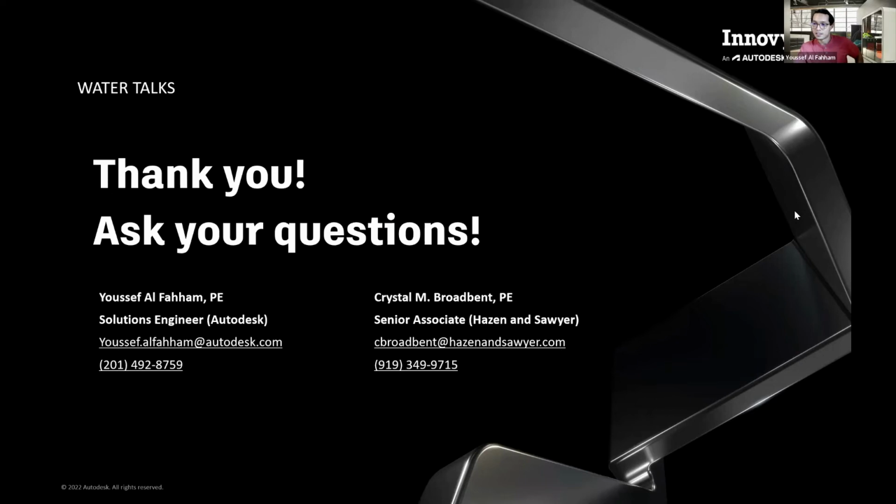Can a check valve at the pump be yes or no, as in Hammer, without inputting timing? On the pump itself, you can say this pump has a check valve. You do need to give it some timing though. Whatever kind of check valve you have, if it's a spring check valve, you can say it closes in 0.1 seconds. If it has some dampening device, you can put 2 seconds, 5 seconds. So you do have to still put a time to it.